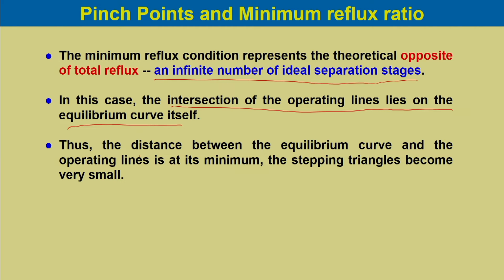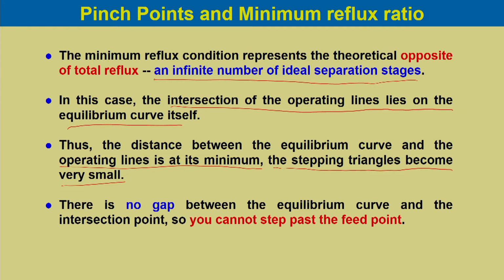Thus, the distance between the equilibrium curve and the operating line is at its minimum. So, at the pinch point the distance is 0, because it is lying on the equilibrium curve. Since it is on the equilibrium curve, if we do the stepping, the triangles become very small as it goes from the starting point to the pinch point, and there is no gap between the equilibrium curve and the intersection point. So, you cannot step past the pinch point.